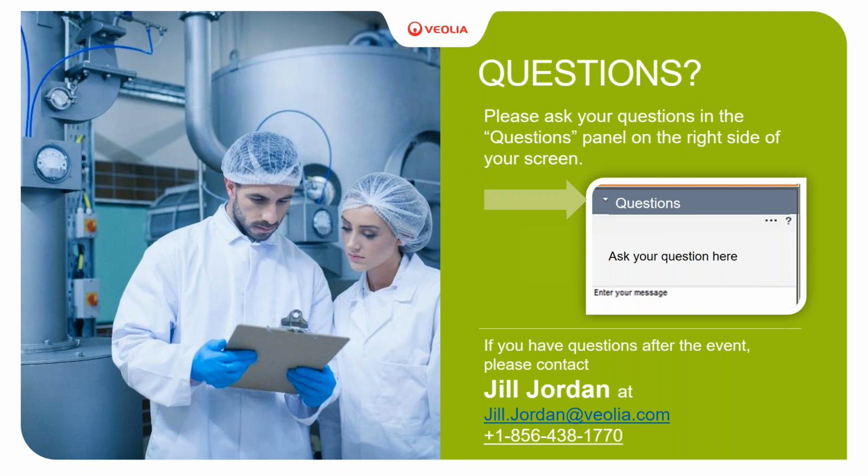The problem is, if you're starting up a lagoon or a CSTR, it's always good to get sludge from a non-municipal lagoon or CSTR, because it will be higher activity biomass than you would see with a municipal sludge. The problem is that the concentration of the CSTR sludge is, let's say, only like 1.5 to 2.5%. So you have to do a lot of trucking, which is the expensive part of the transfer.